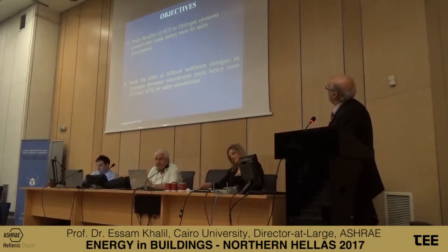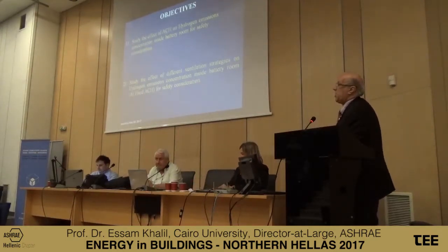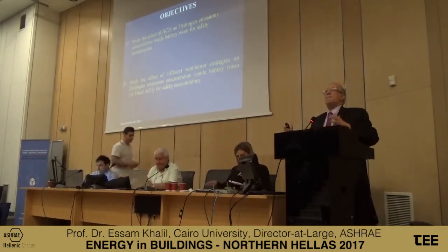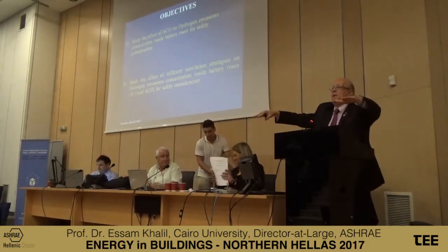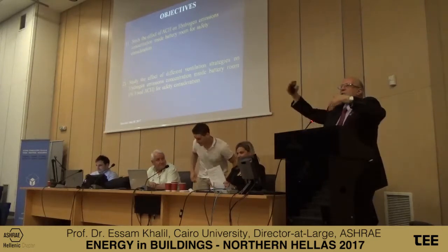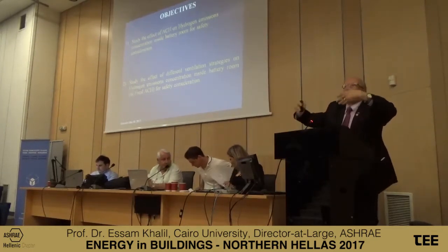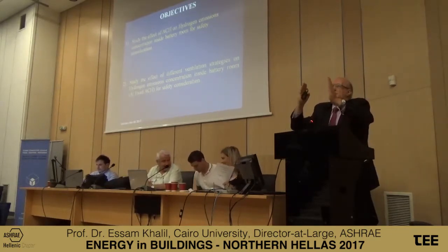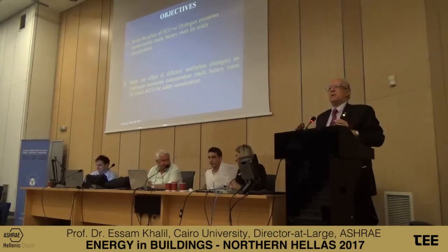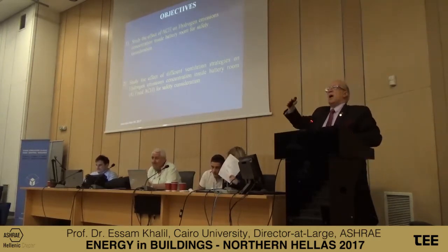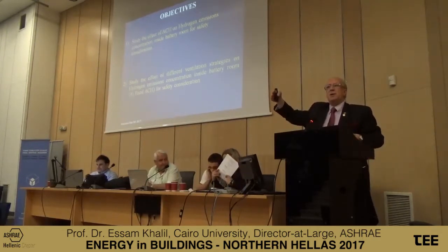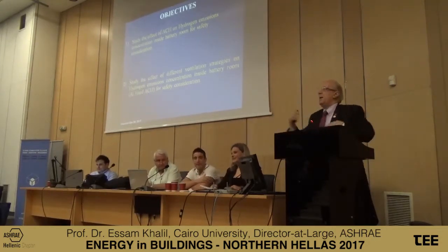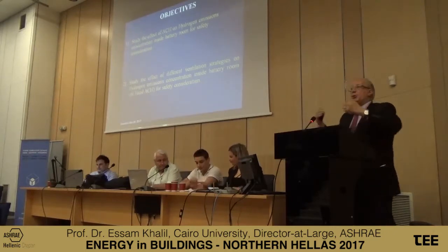So here, for example, the objective is to study the effect of changing the air. ACH is air change per hour. If I'm ventilating this room, then I would like to change the air in this room 2 times, 3 times, 5 times per hour. Actually, give us a value for each application. Of course, if you put higher air change per hour, you are going to use a bigger fan, you're going to pay more money and more energy. So we'd like to reduce this.